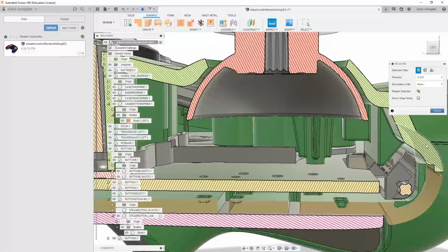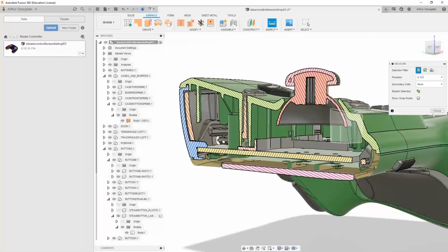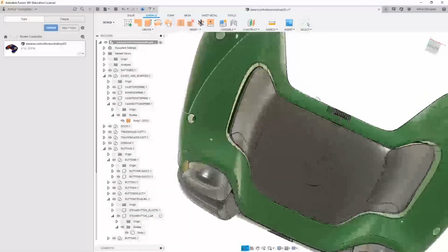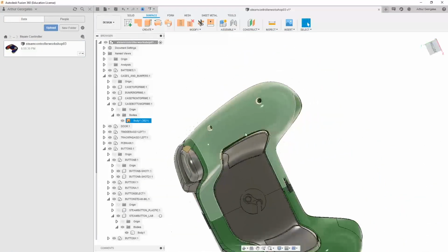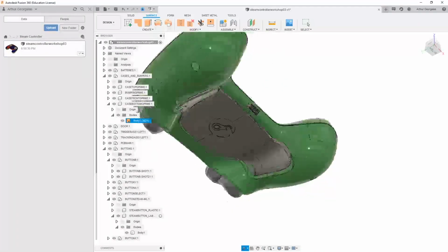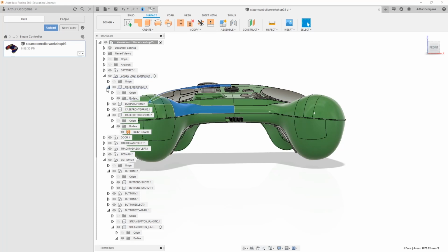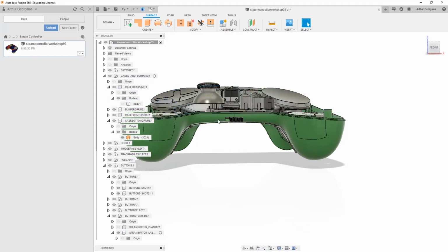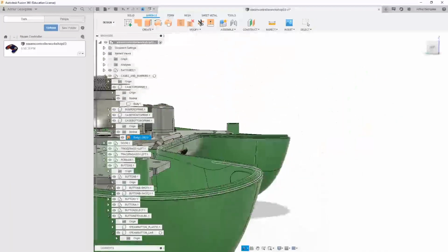And we can see that it has a groove where the 2 pieces can snap onto each other, and let's just close that and turn off that analysis. And then it's got actual holes in the bottom where the controller can be held together by some actual screws. So we don't have a snap together on the groove on the inside. What it does is just hold it in place and line everything up, and then the screws pull it all together in a way where it can't come apart.